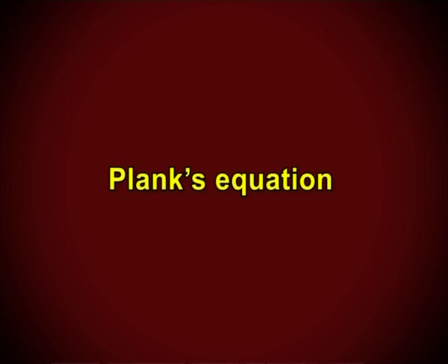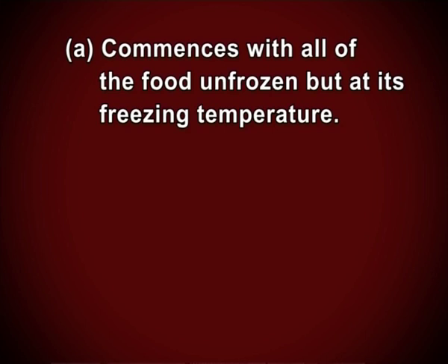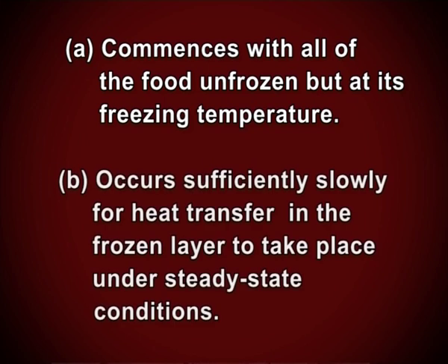4. Planck's equation. The freezing time is the time taken to lower the temperature of the product from its initial temperature to a given temperature at its thermal center. Planck's equation is an approximate analytical solution for a simplified phase change model. Planck assumed that the freezing process: A, commences with all of the food unfrozen but at its freezing temperature; B, occurs sufficiently slowly for heat transfer in the frozen layer to take place under steady-state conditions.